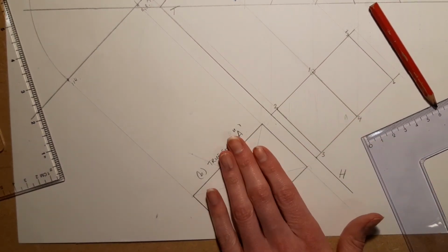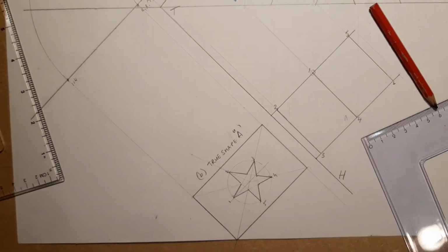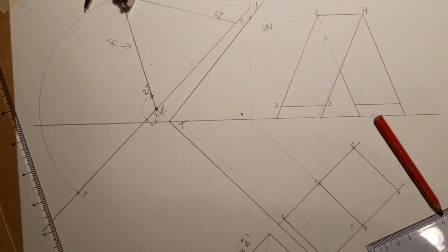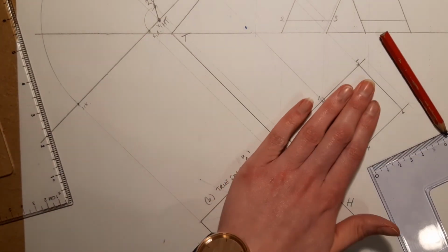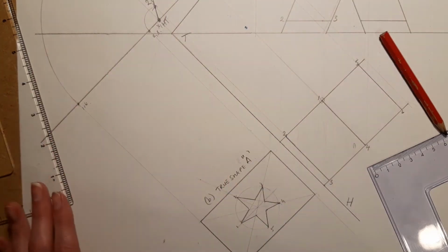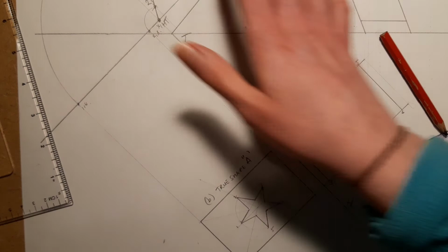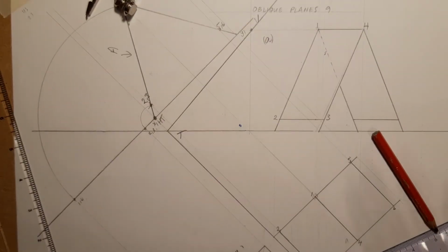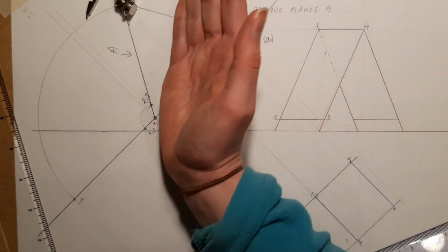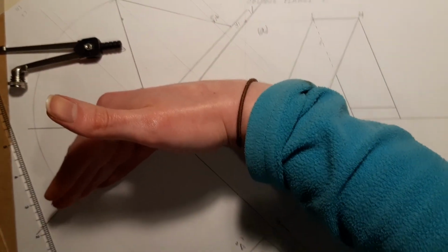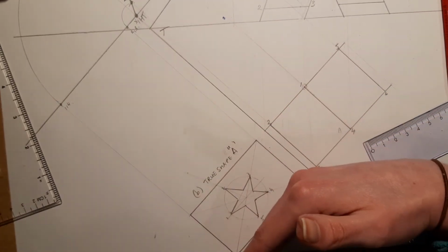Once you have your 5 points, I need to transfer this shape onto that surface, and then on that surface up into elevation. So I need to go through all of the views. Now, it's not just as simple as, oh, let's bring back these 5 points and let's bring them up. We have absolutely no heights. So we need to bring them back in the way we brought everything down. So the way we moved from this is we had the elevation and plan done. We moved to the auxiliary, we moved to the rotation, and then we moved down to the rebatment. So we have to work backwards.